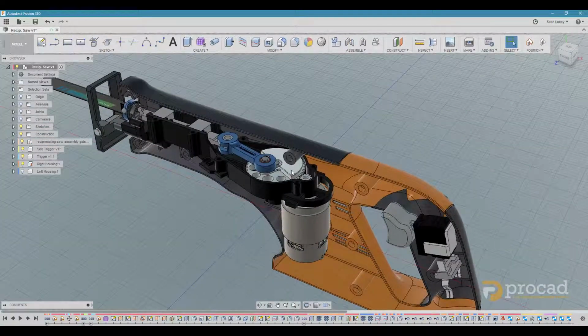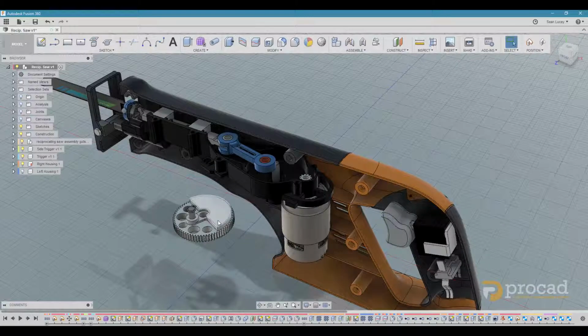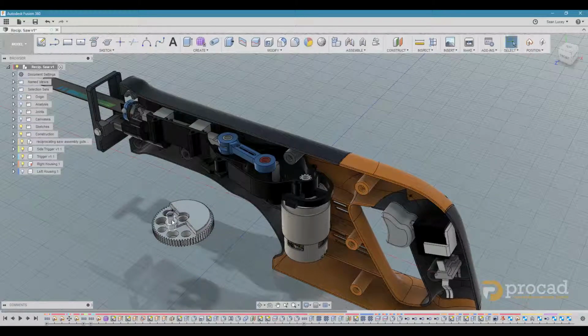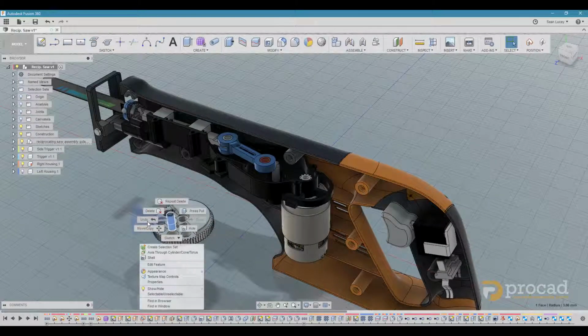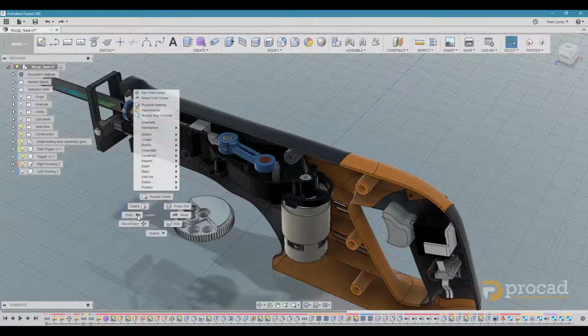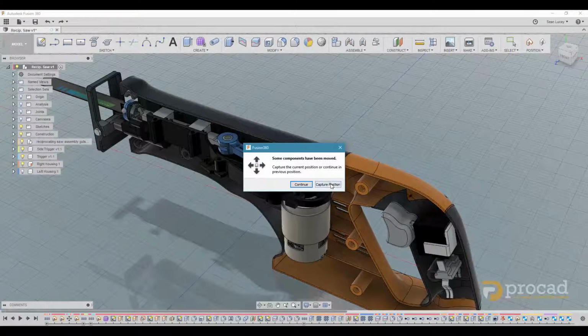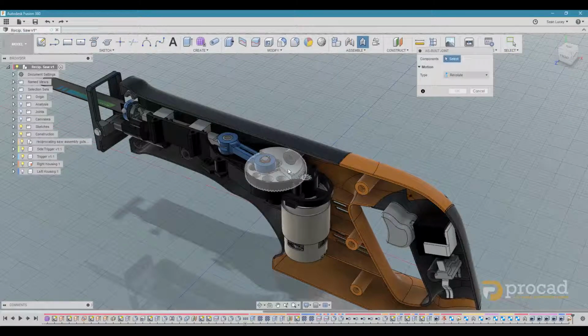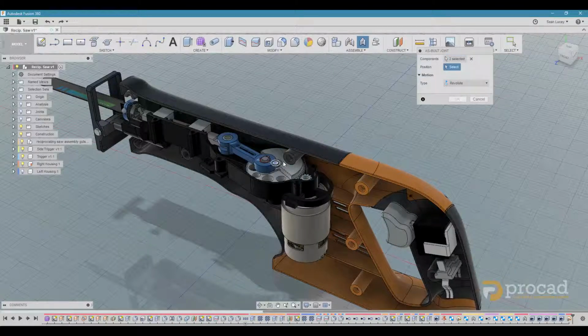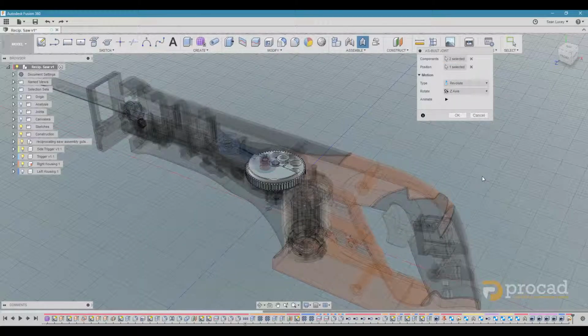As you can see in this model, the componentry is not constrained. This model was created with a top-down modeling approach. This means that all components have been created in position to one another and is the perfect use scenario for as-built joints. Geometrical constraints in Fusion 360 are known as joints and come in two forms: standard joints and as-built joints. Both features are located in the Assemble drop-down menu in your modeling environment ribbon.